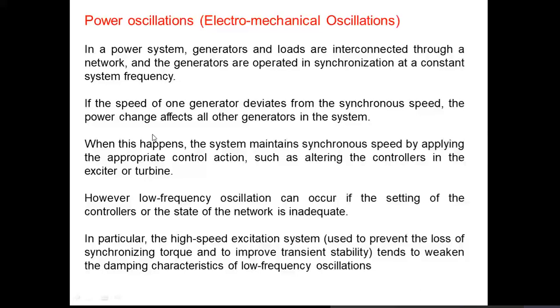So if the speed of one of the generators deviates from the synchronous speed, then it will indicate an imbalance. There is an imbalance between the power available from the generator side and the power demand from the load side. And thus the deviation in the frequency will reflect the power change in the system.